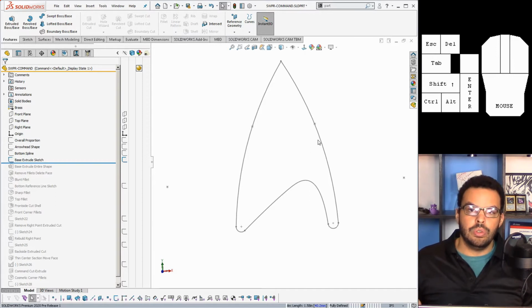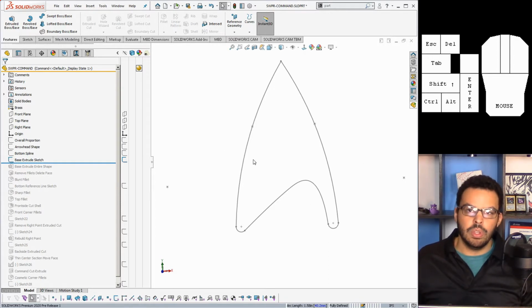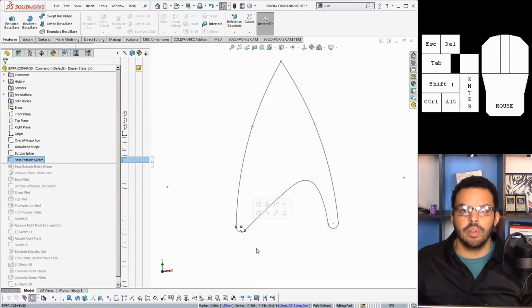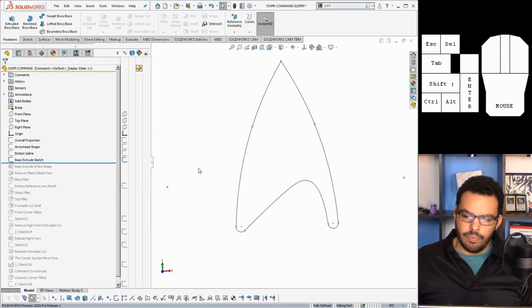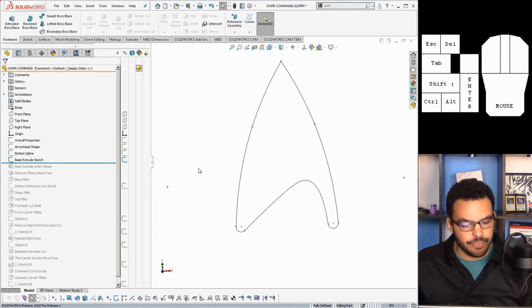I can actually use the scale tool to make sure it's the right height, and then just trace it in another sketch, with splines or analytical geometry like an arc or whatever, and then work from there. I don't think one way is better than the other. The main downfall of using a sketch picture is that you need a picture. Sometimes you don't have that, and the best thing you can do is this.